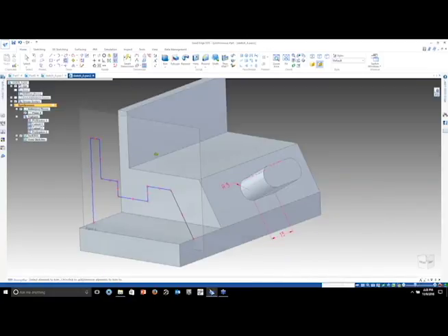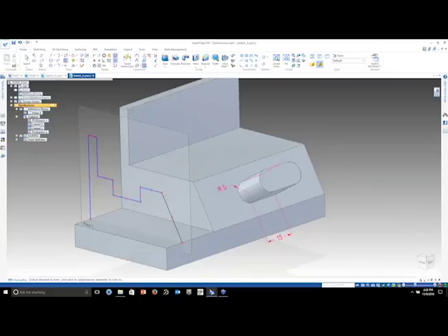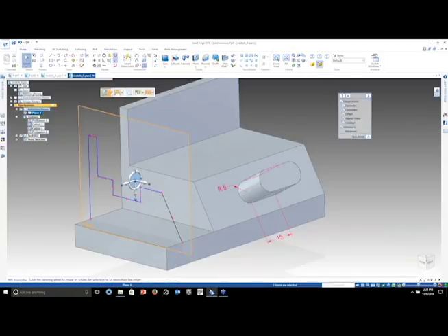All right, so again, now I have the trim tool at my disposal. I'm going to just go ahead and left click and hold down and drag through where I want to remove. So I want to remove that. And the same thing here, left click and hold and drag. I want to go ahead and get rid of those lines. There we go. All right, so now I have a piece of geometry here. I can go ahead and extrude.